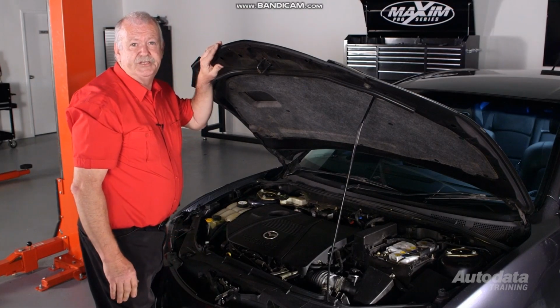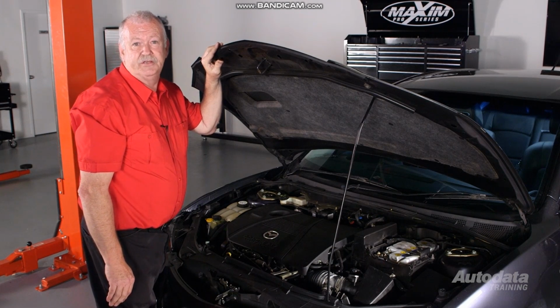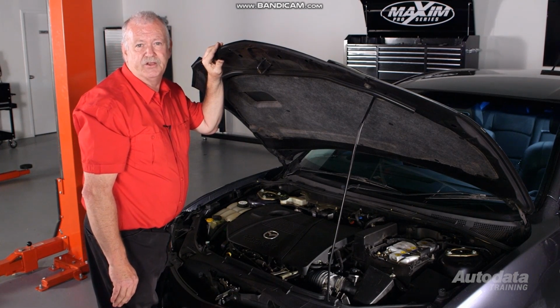There you have the diagnosis for P0102. Check all areas of concern. Don't assume things are correct. Test them. And as with all DTCs, once you've found the fault, clear the codes, take it on the appropriate drive cycle and retest.